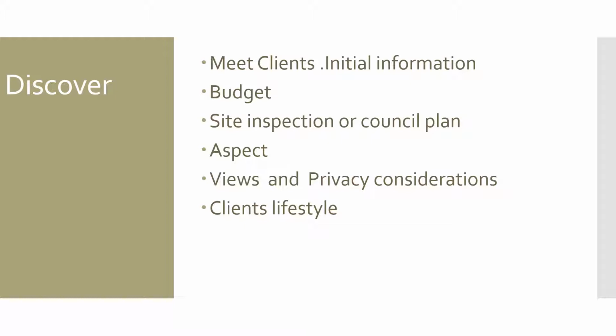So the first stage is meeting the clients, obviously, and getting all the initial information from them, which will be the size of the house, how many bedrooms they want, how many cars they have, how big their family is, and then finding out where they're building and what sort of budget they have for the building. And that meeting will be the first stage, and then go on to really looking up the block on the council website, or seeking some information from council.